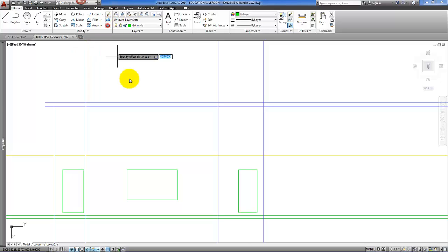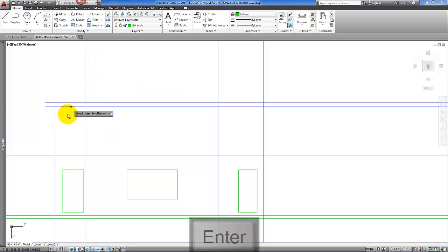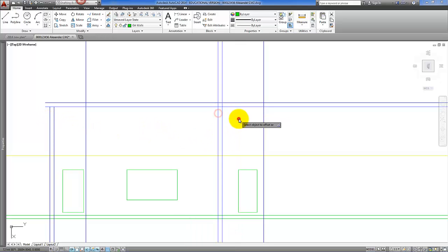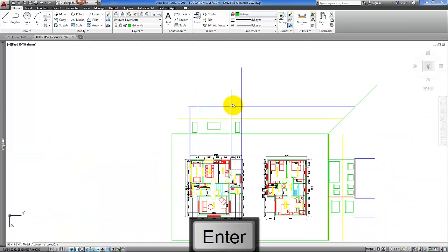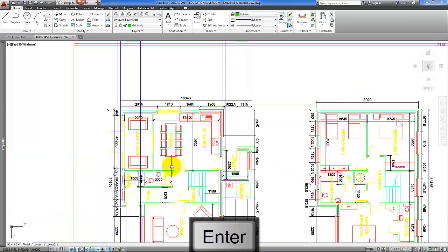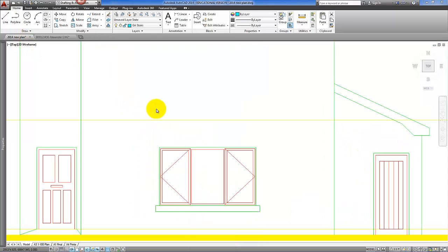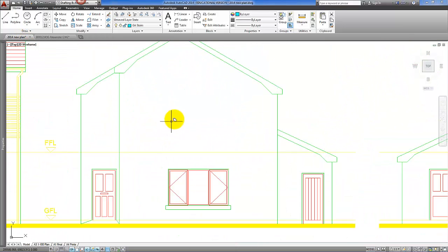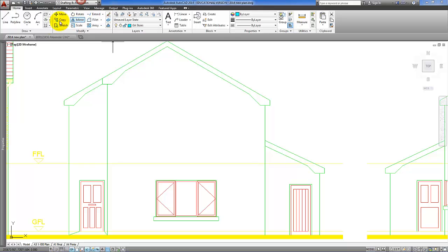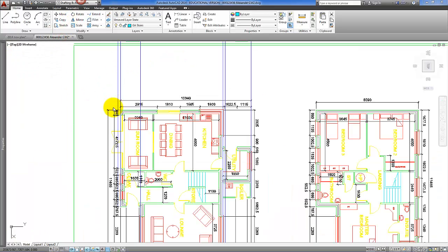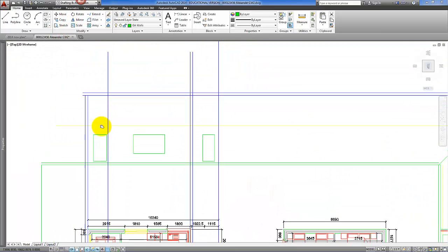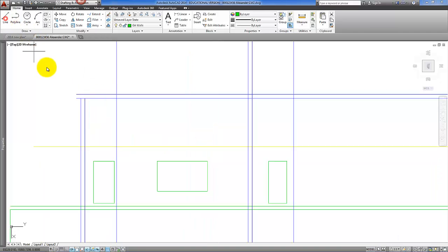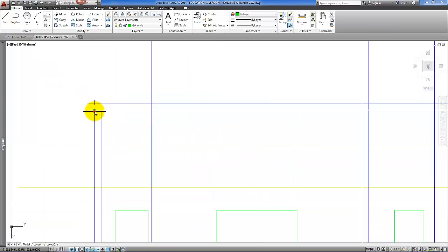So let's offset by 200 millimeters to get the level of front fascia, and then it's this line here really that we need to use for the back of the house, because this is the main part of the roof. Just to have a preview, this is going to be the elevation here. So we offset there already by 200, and we can draw in the line of where the fascia would be.